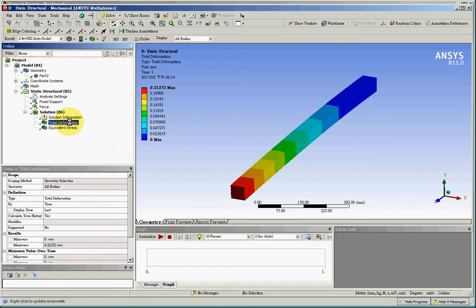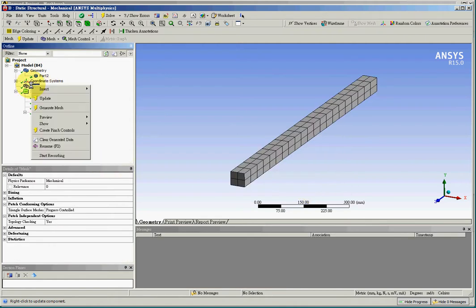And for the result, first of all, we'll see if the unit is what we need. Actually, it is the unit that I need in millimeters. So I can probe the deformation here. It is 0.2125. And I can make the mesh finer.